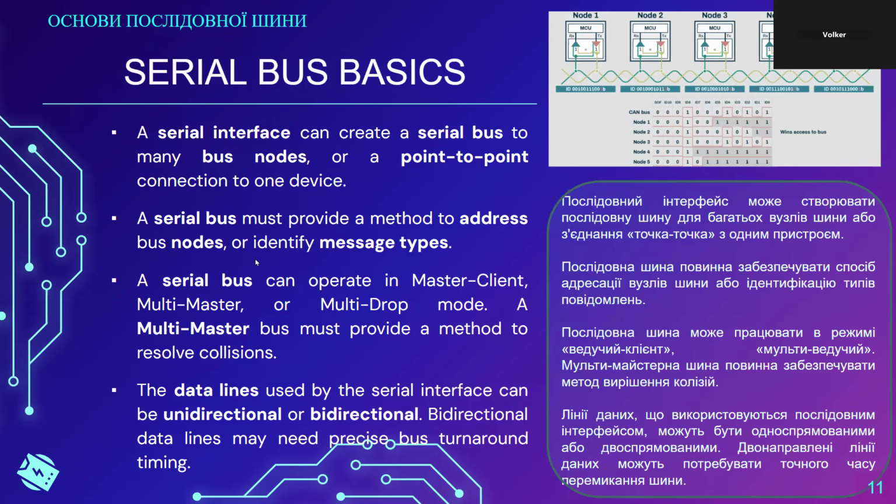Usually we think of a serial bus as something where every bus node can be addressed. It's kind of normal to think that a device on the bus can be directly talked to. That is not always the case. It is the case, for example, for the I2C bus, but the CAN bus, for example, only knows message types, message IDs, because there were two different philosophies behind this.